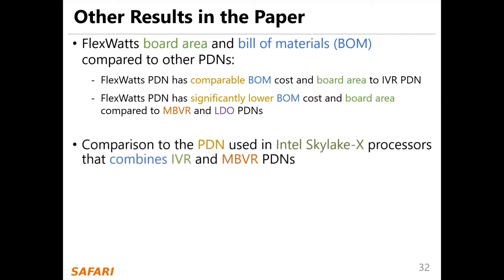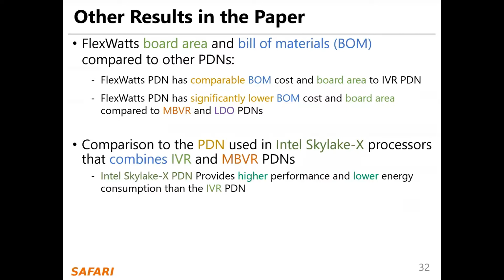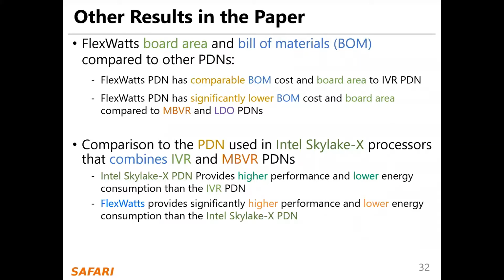Comparison to the PDN used in Intel Skylake X processors, which combines IVR and MPVR PDNs. The Intel Skylake X PDN provides higher performance and lower energy consumption than IVR PDN. FlexWatts provides significantly higher performance and lower energy consumption than the Intel Skylake X PDN.